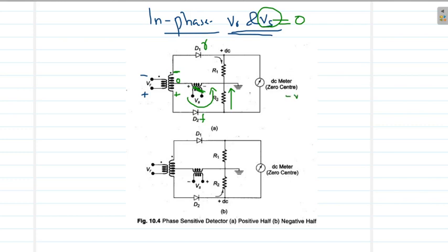So during the negative half cycle, the galvanometer will indicate a left deflection. So during the positive half cycle, we had current conduction in this direction along R1 downwards, and the galvanometer indicated a right deflection, and during the negative half cycle, diode 2 conducts and R2 has a voltage which allows a current to flow in this direction, upward, and the galvanometer will show a left deflection. Now we know any signal consists of a large number of positive and negative half cycles, which are repeated